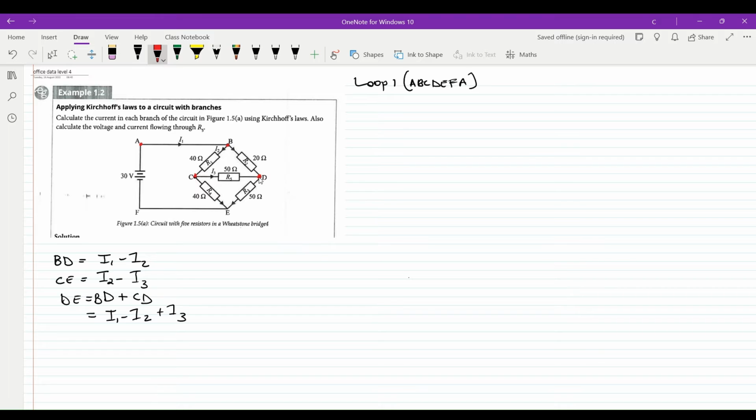CD, do I have a resistor? Yes, and also current is here. Then there is an existing volt drop here. DE, do I have a resistor as well? Of course, and there is current also involved here. That means we are going to have a volt drop here. But if you look at EF and FA, we don't have resistors. So the only voltage that will exist here will be the total voltage supplied by this circuit. Let us put that in writing. The first thing that we'll do, we'll write it as ET is equal to. We said that AB has nothing, therefore we don't even waste our time writing a zero. We'll just move along.